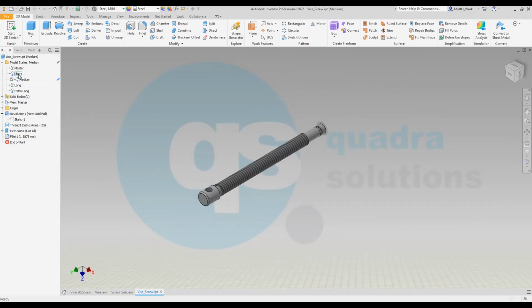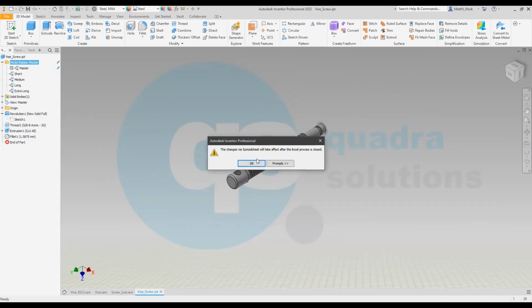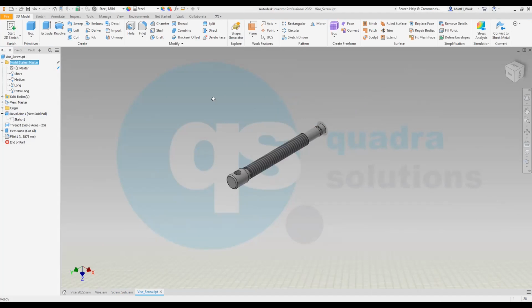And we can see there that those values within the sketch are then held within the file. Just like you do with an iPart, iAssembly, you can edit this via spreadsheet. So once you've created an example of the thing, once you've decided to start driving a particular value parameter, you could then use your spreadsheet to drop in all the different configurations. It might be easier to build the spreadsheet, copy and paste, etc., than it would be to build individual lengths.